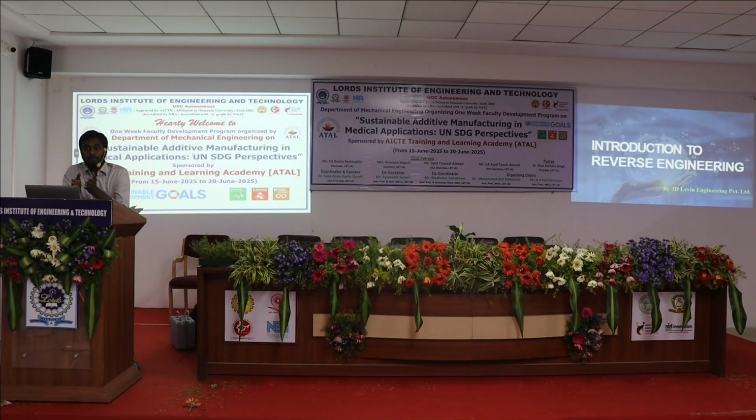Then we get raw data, known as mesh files, and we extract the dimensions from the data with the help of software like Geomagic, PointShape, NX, Creo, and then we go for production. Here we use 3D scanners to scan the products, which are manufactured as laser scanners, white light scanners, and structured light scanners.